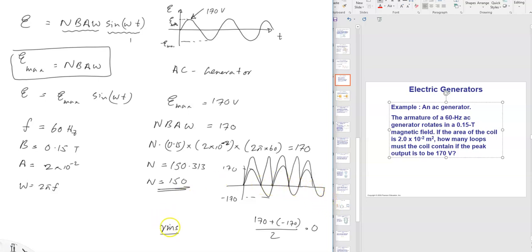Like this. And then that's the squaring. You take the mean, or you take the average of this. Right? You add them all together. Now it's all positive numbers. You get the mean value. And then you take the square root of it. So you bring it back to what it was. So that's the operation, RMS value.